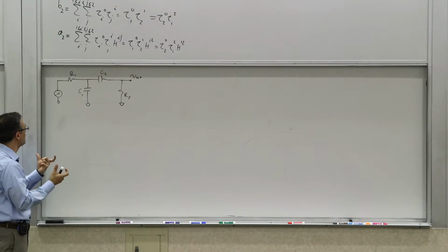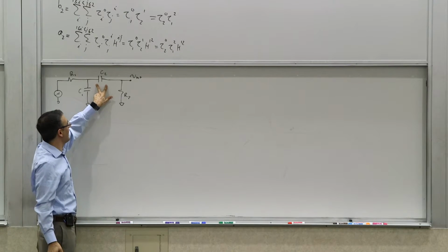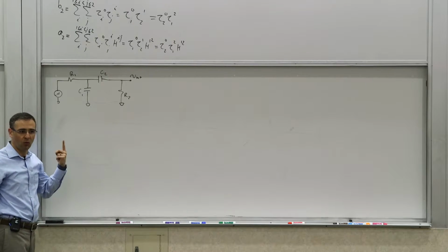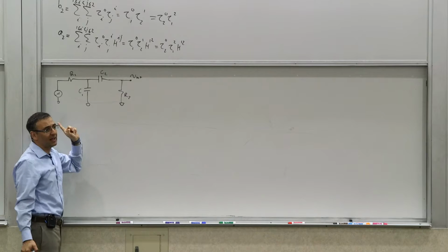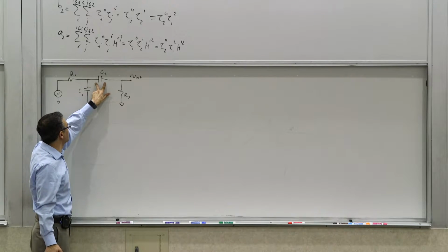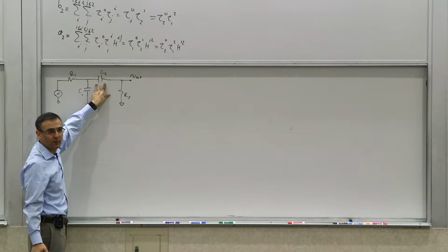Two. We can define two initial conditions. I can set this to 1 volt and this to 357 volts, and nothing will happen, right? I have 2 degrees of freedom. Now, how many zeros? One. The maximum number of elements that can be simultaneously infinite valued is 1, because I can only make this one infinite and get a non-zero transfer constant.